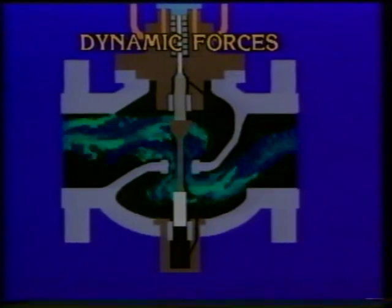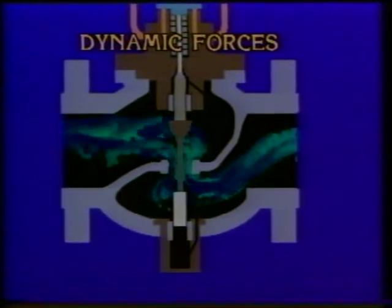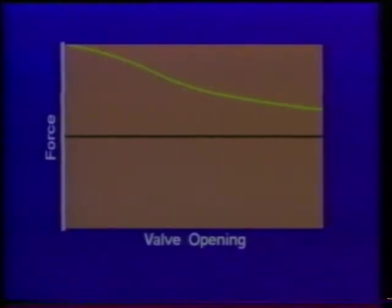Now, let's look at what happens to forces as a valve opens and fluid begins to flow. These are the dynamic forces and can be extremely complex. We'll use a graph to illustrate how these forces can vary as valve opening increases. This plot represents the dynamic force on the plug in a quick opening globe valve when flow is tending to open the valve.